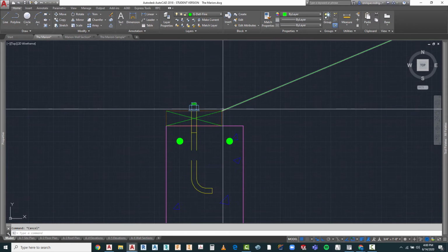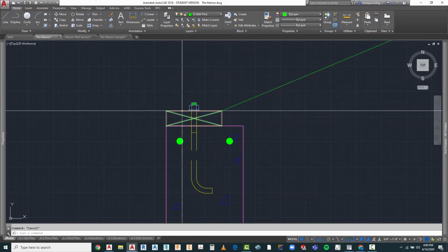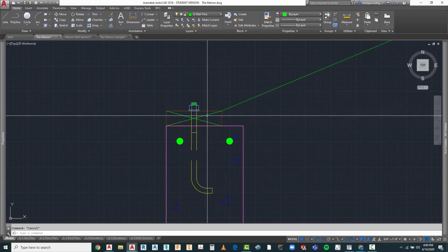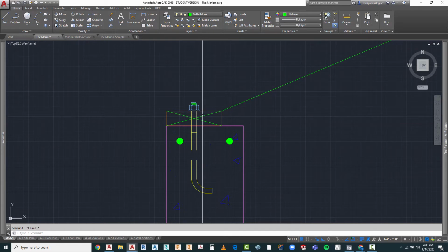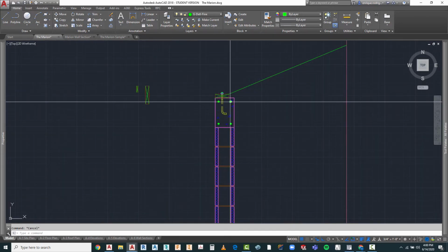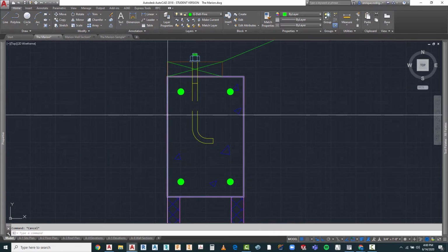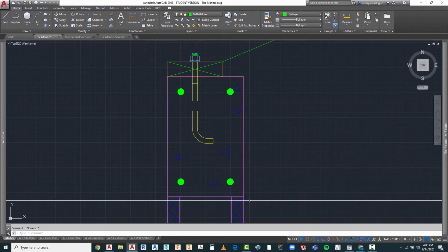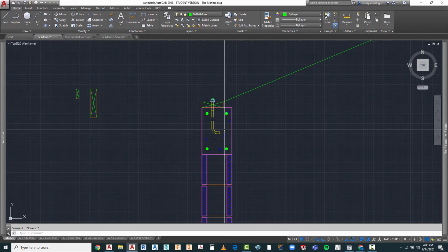Now it doesn't necessarily have to be on this corner. Usually on a wood-to-wood connection you don't need the full bearing capacity that you have here. What you need is probably 2-3 inches. Code will describe what that capacity needs to be. So once again, just like what we were talking about, block only being 7 5/8 inches wide instead of the nominal 8, the same thing applies with wood.